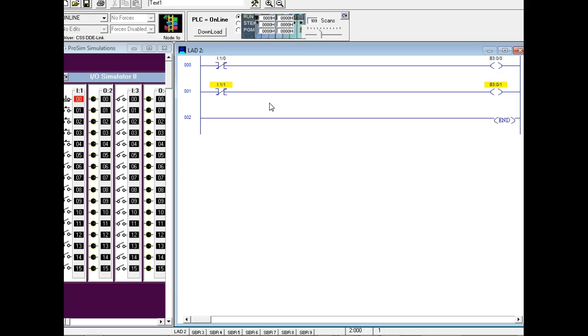Normally closed input with the examine closed. So it's true all the time, right? And this other one is false all the time. So this is the examine open, and I've got a normally closed push button. I've got it set for examine what? Open. So what's it give? It's false. And so the normally closed contact is false, right? You understand? So that would give you an error with it.